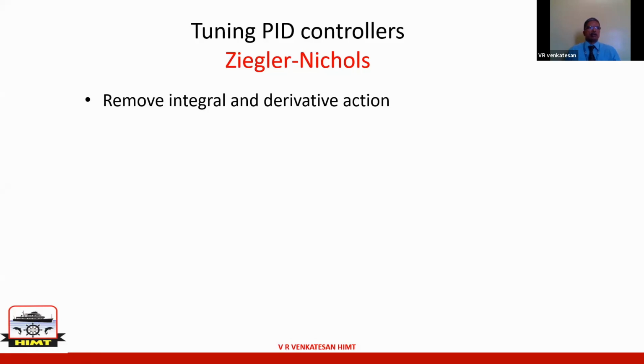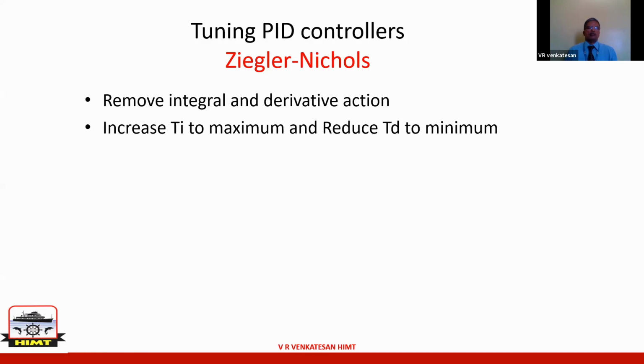So how do I compensate for this? If the output is sluggish, what should I do? Increase the integral gain. I should increase gain. If I increase gain, then the output will be increased. But later on, somebody else comes and solves this problem, the leakage is fixed. Then what happens is the gain will be excessive. So in a lot of vessels, the adjustment itself can be wrong. Because the adjustment is wrong, tuning may be required again. So understanding tuning is important.